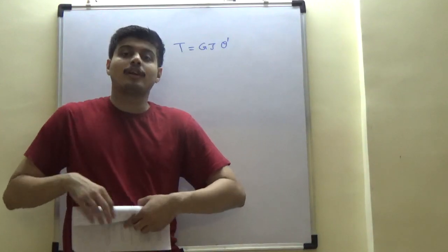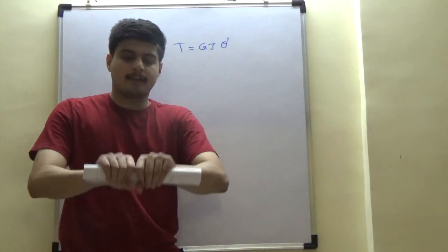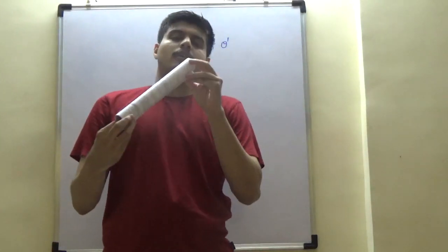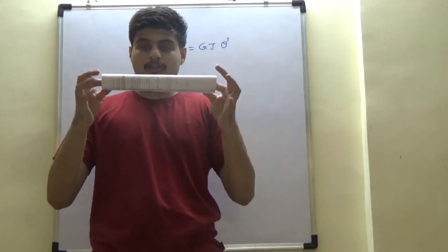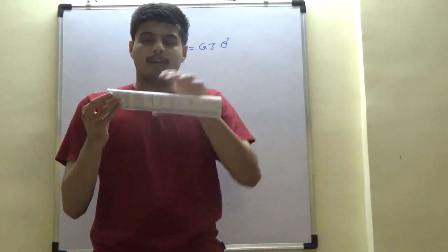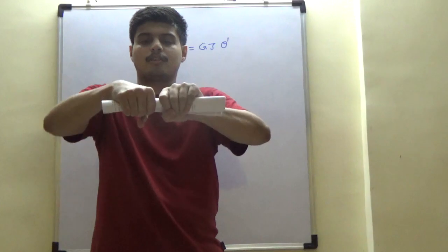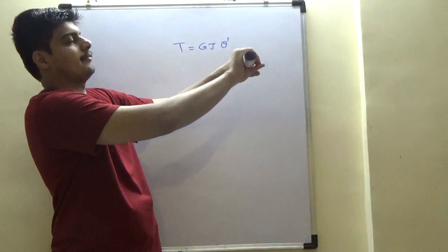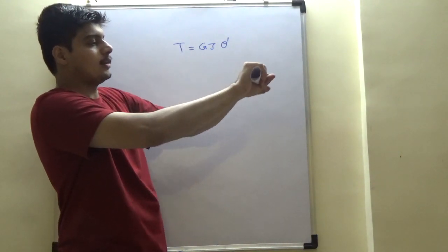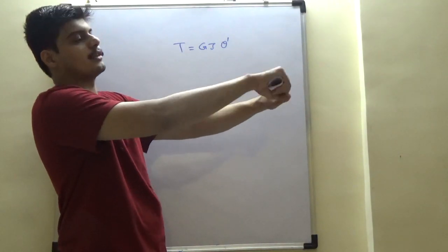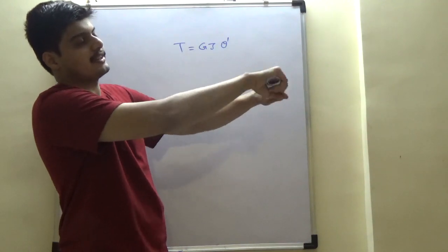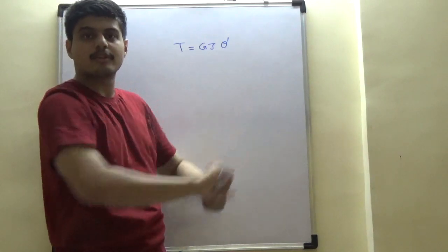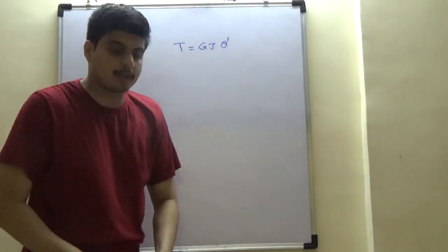This is one of the first qualitative tutorial problems you could consider. This sheet, which is open and not restricted from any warping, right? See how easy it is to bend this sheet. These are open sections, right? Moment I glue them, it becomes more complicated. You see how it is easy, right? The J of these open structures is extremely small. You can easily do it.